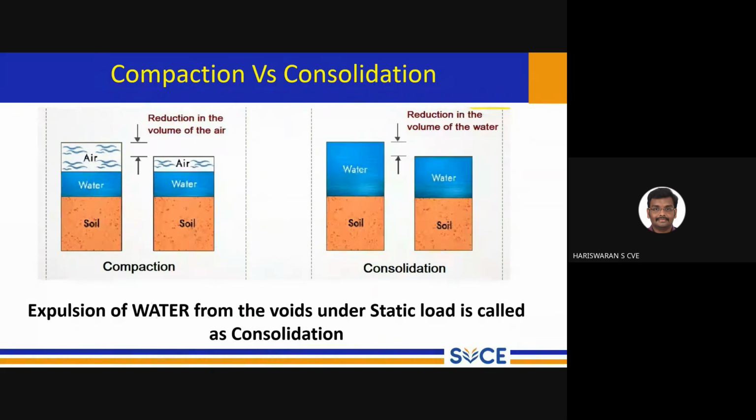If you have a clay soil, or if you are in a teaching community, you can practice in the laboratory. If you are taking a wet soil sample, above that you can apply any constant load, say 1 kg. Immediately once you have applied the load, you can't see any change in the compression. You just observe after 1 day, then after a week, after a month, repeatedly. If you keep on observing, due to the applied load, the thickness of the soil is slowly reducing by dissipating water from the soil.